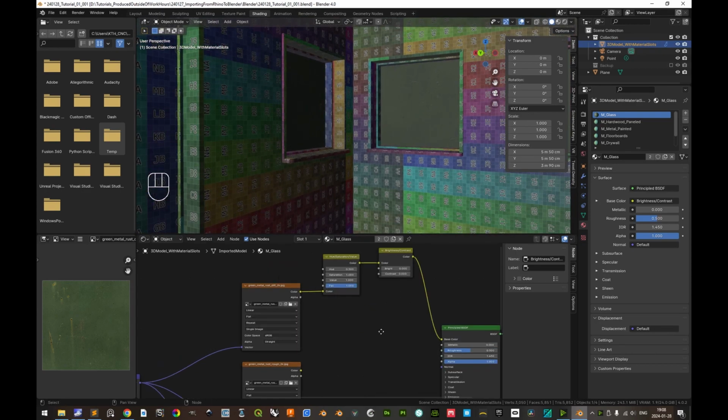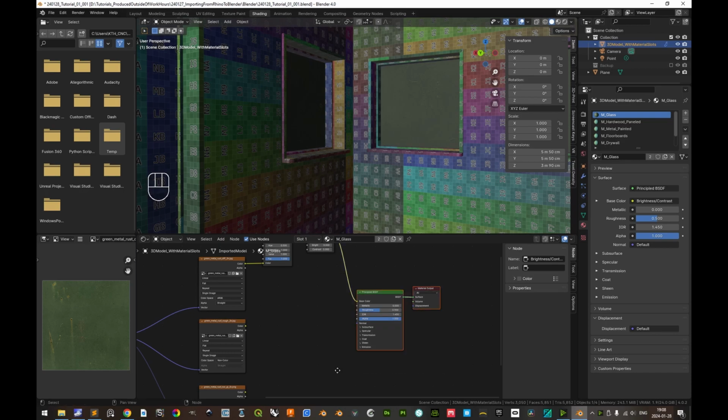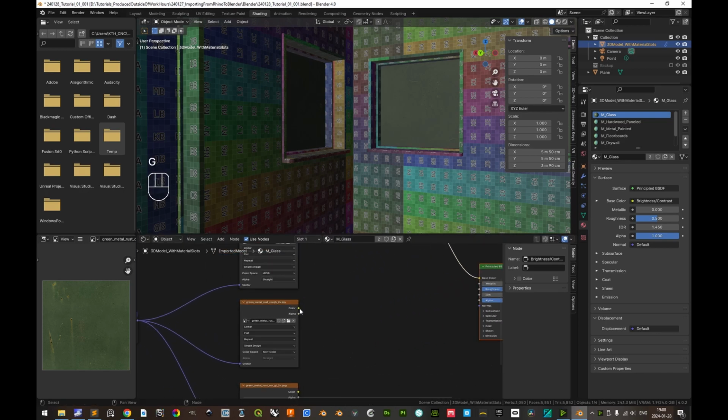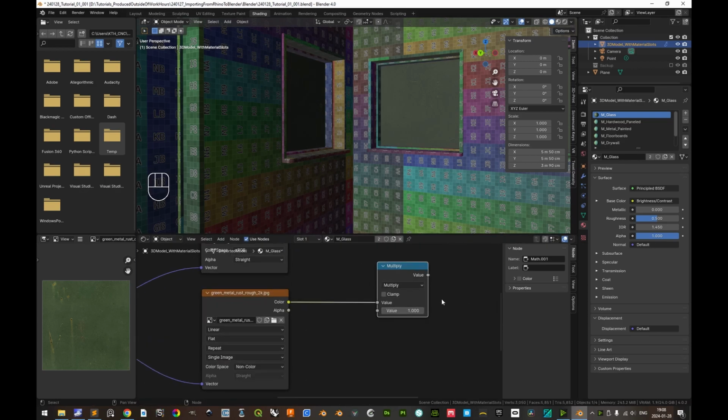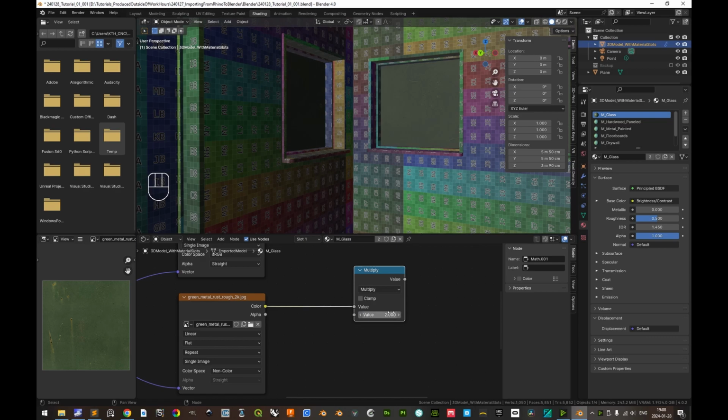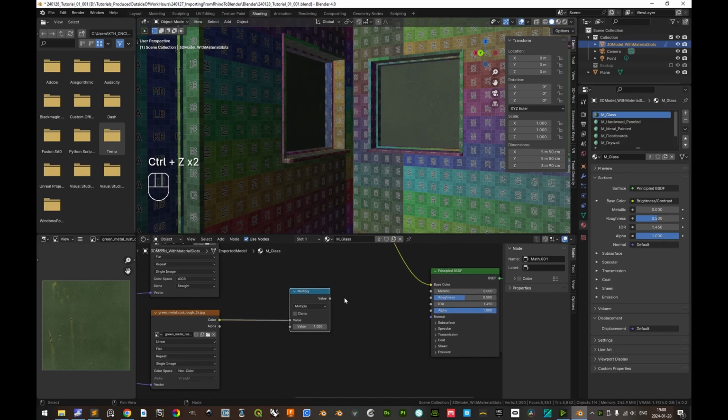Very good. All right, and as for the continuing work of this template, let's make sure that the roughness value, it should be able to be multiplied, and that is not a vector math, it is simply a math because it's a linear value of a single scale. And then the value here, it should be set as default 1, and then it can be multiplied, and it can be doubled, or it can be halved, and etc. Let's Ctrl Z to undo. All right, this should be input into the roughness input of the shader.